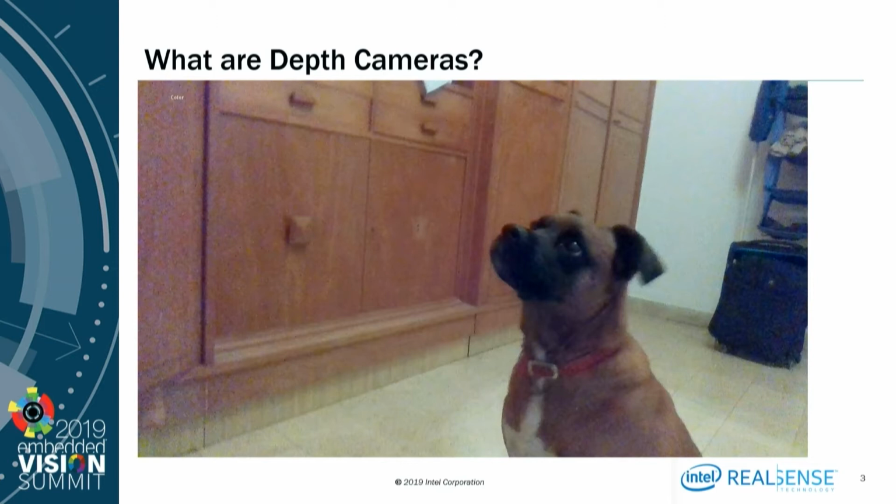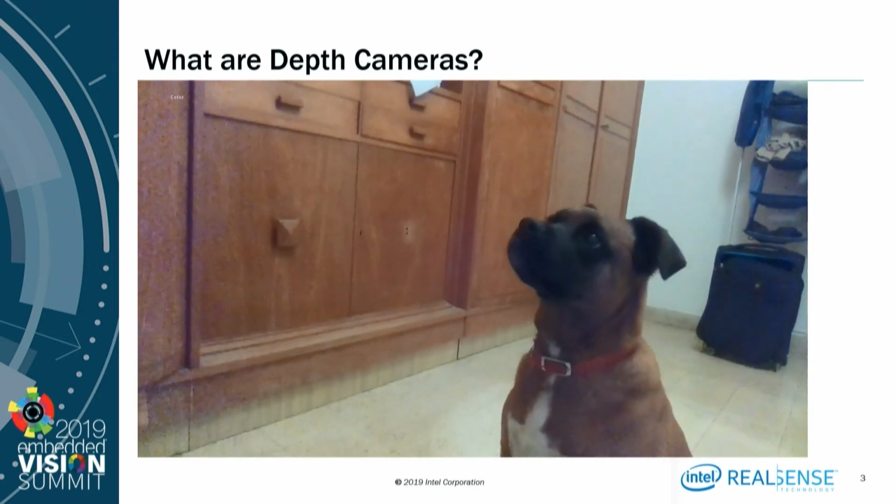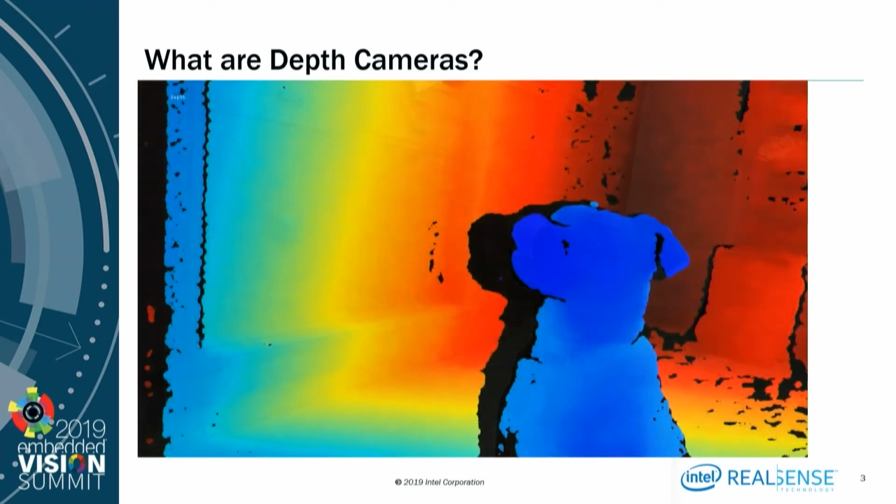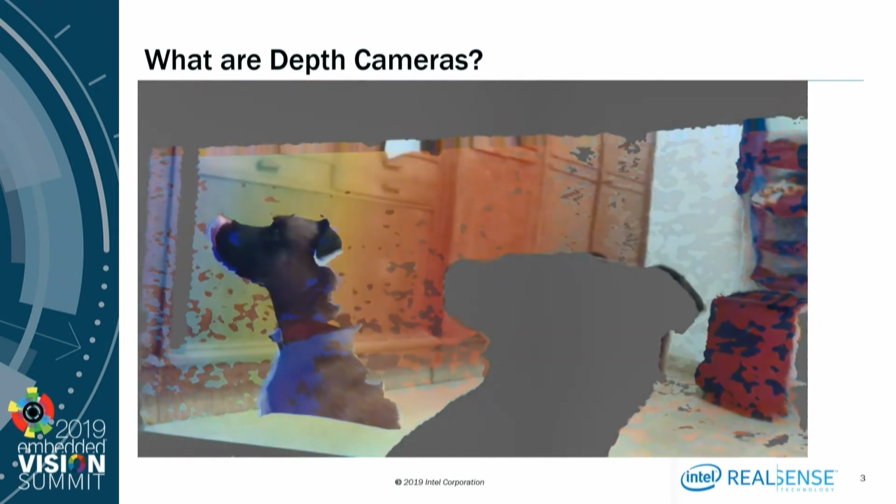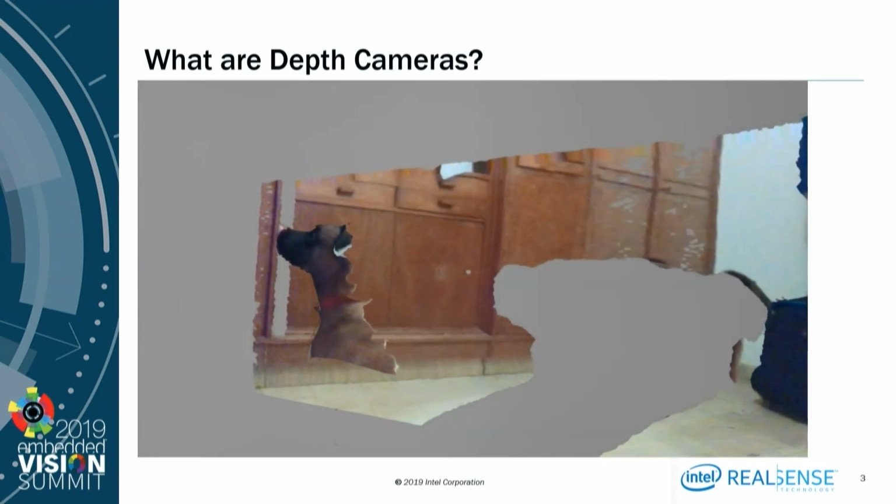with an overview of what is depth sensing and what differs a depth camera from a regular webcam. So in addition to the regular RGB information provided by a webcam, a depth camera is also providing a layer of depth with every frame, which contains for every pixel its distance to the camera. Using this information, you can think of every frame from a depth camera as a standalone snapshot in 3D of the environment, capturing the geometry and the distances in the environment.